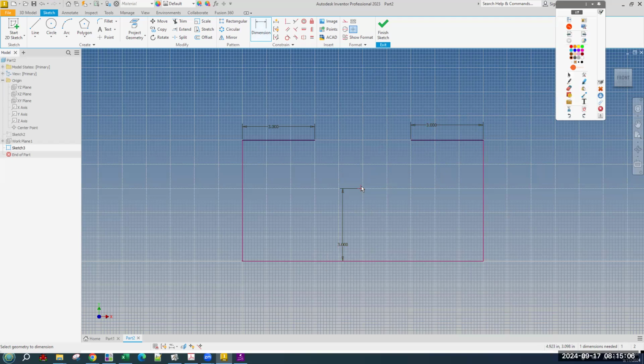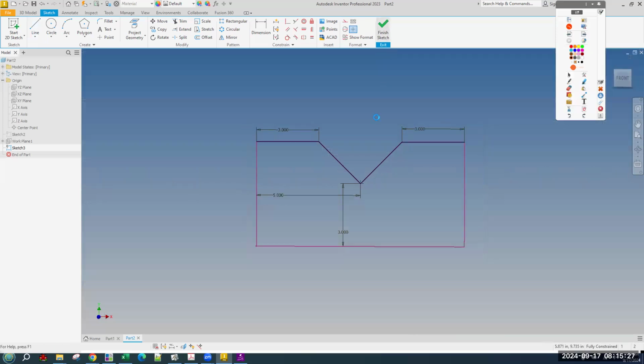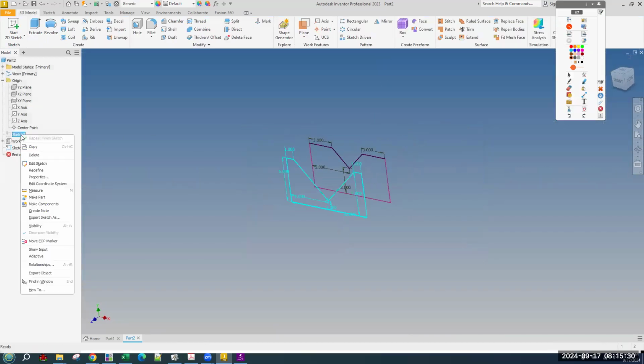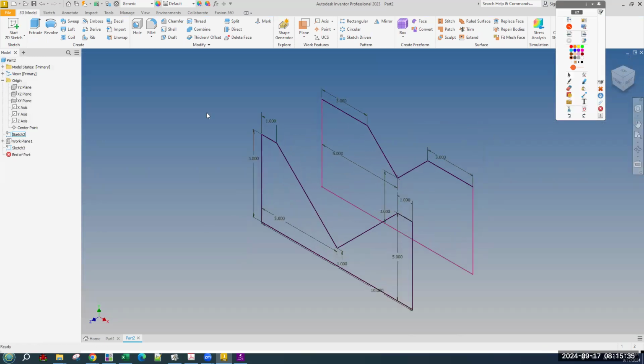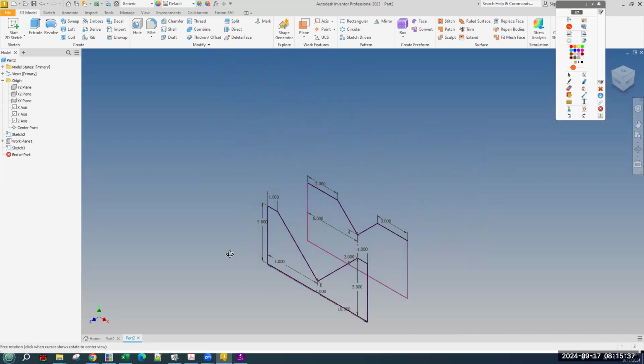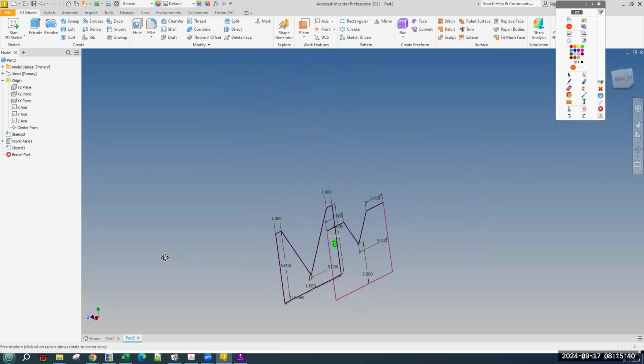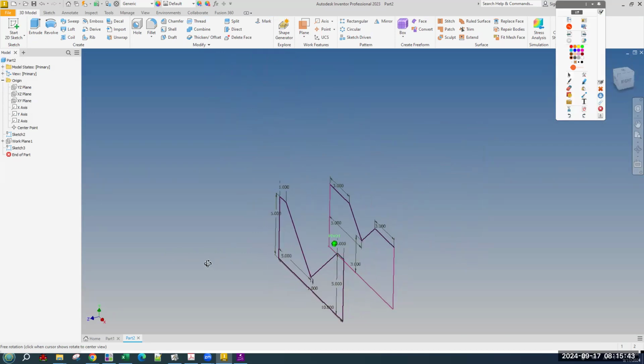And then the other direction we need to dimension is the distance between the center point and either side, either of which will be a distance of 5. Now we have our point right there. Let's get a line from there into there and then connect over. Okay, and we can finish sketch. And let's turn the visibility of our first sketch back on. Right, check visibility. And now we have 2 sketches. Okay, and they are 4 inches apart.